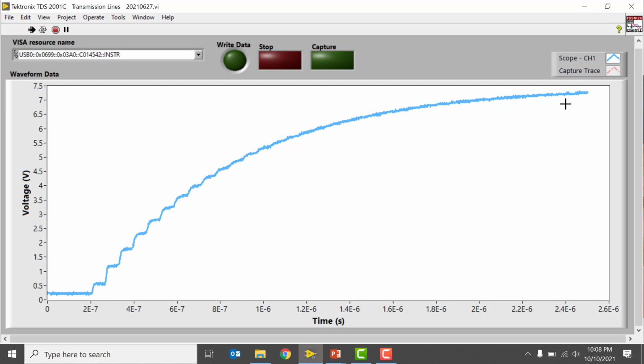And again, that's a behavior that's pretty complicated for what's really quite a simple experimental setup. It's just a long transmission line and a 1 kilo ohm resistor, and then we hit the input of that with a voltage step. Just to finish things off, I'll show you one more thing. Right now, our transmission line just has an open circuit at its far end. And so I'm just going to insert a short circuit, and we'll see how that changes things.